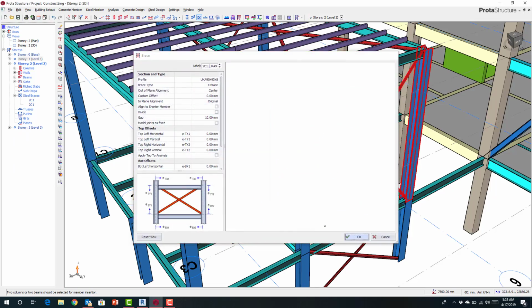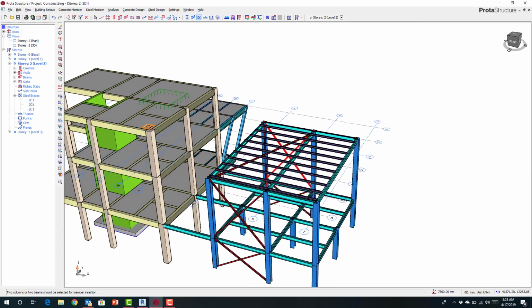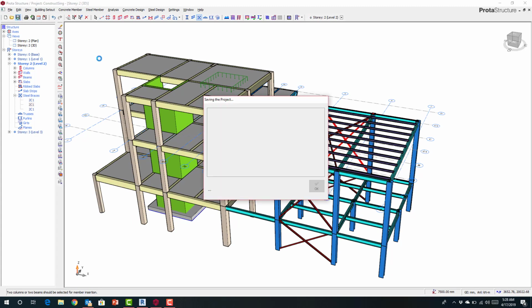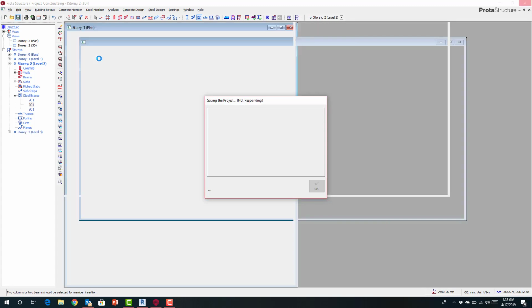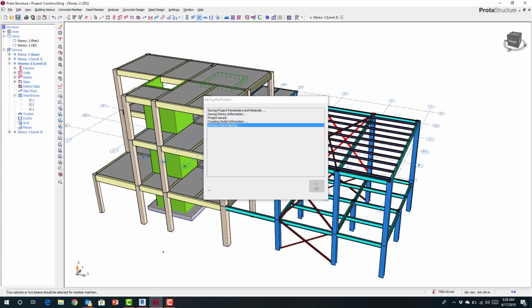At the same time, you may also update the design. You may do some design checks. You may continue with the analysis processes. But at this point, when you want to communicate the changes that have occurred as a consequence of the ongoing design back into Revit, make sure you save the model again. So just update the model here and save that, and let that finish saving.